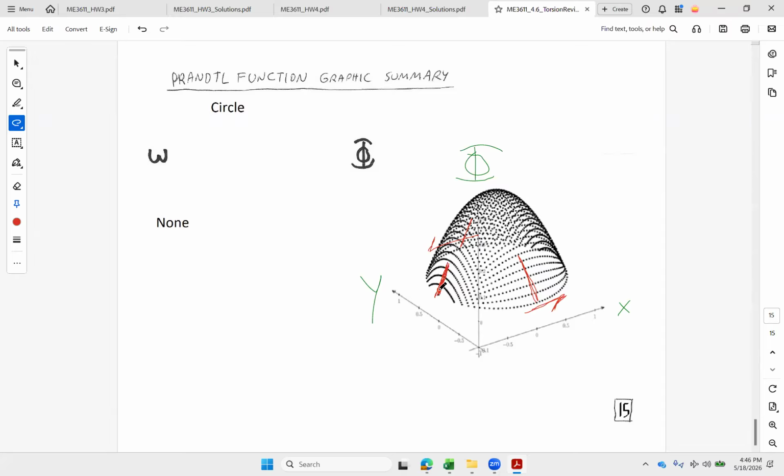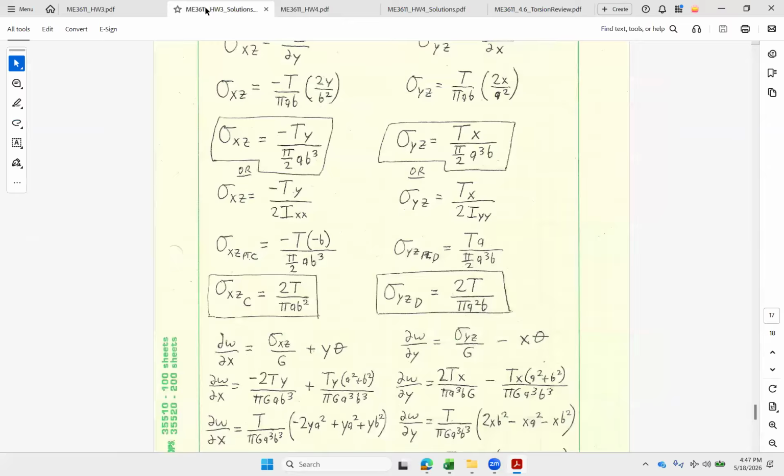That's my stress in the y direction. So if I try that out, here I have a maximum x slope, no y slope, and that's minus d Prandtl dx. So my stress goes against y. And over here, I'm running downhill real fast in the x direction, no slope across the y. So I'm going to get all stress this way, and the sign change points it up. So there I can see it goes around in the circle, just like I think it should.